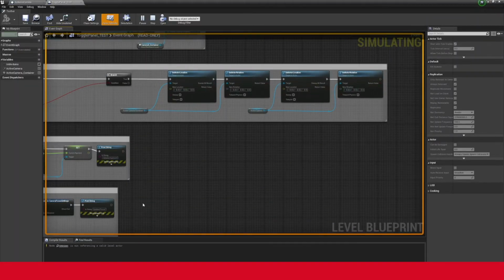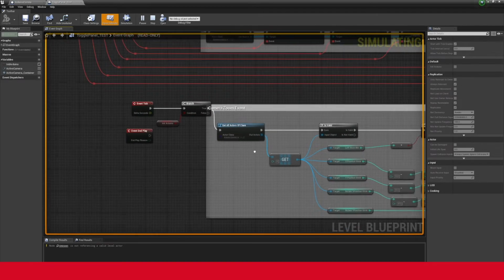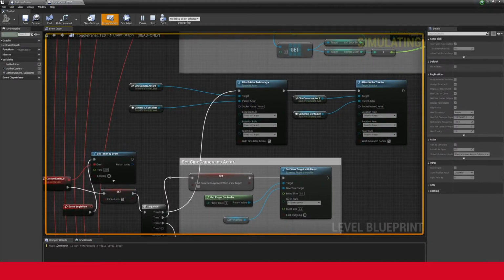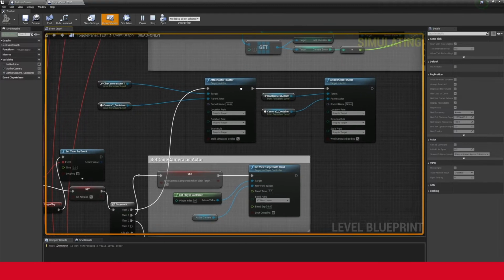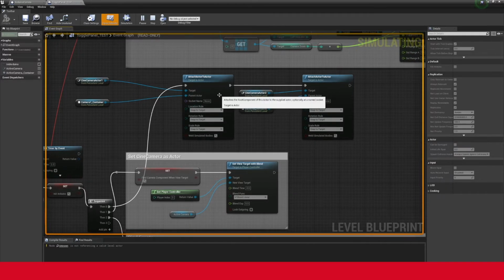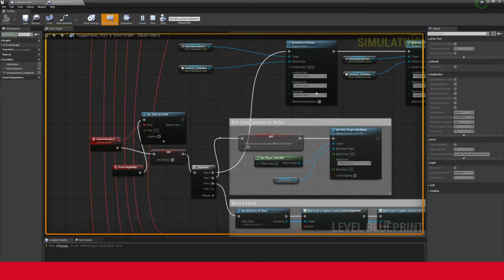Just give it some more space. And there are a few different things happening here. So the first one is on setup, we essentially assign the camera to a container, right? The reason we do this is we don't want to deal with the local translation and rotation of the camera. We want to do it on the container so we can reset that container. The camera is being controlled purely by the HTC Vive tracker in LiveLink, so that must be driven by that, and the container can be driven by our joysticks, right? So we put the camera in a container and we snap them together, essentially.